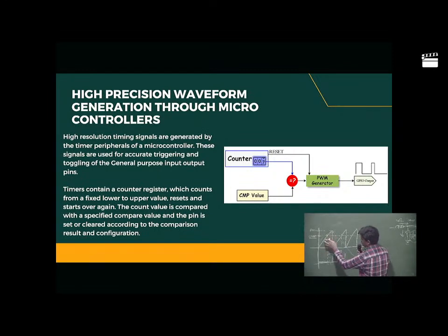So if this is a period value and I decrease it, say this was 65,000 and I set the period to 32,000, this is also something I can define. It will count like this, reset, and reset again. So the amplitude of the signal can also be varied. Hopefully you get the idea with that. It's going to be a little messy and we are short on time. So this is how we can accurately create a control wave using microprocessor code.